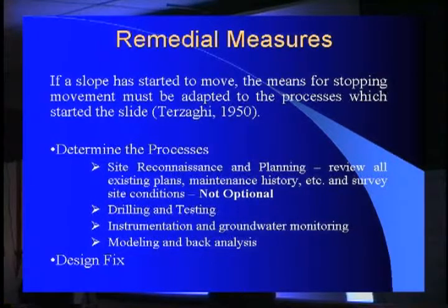Drilling and testing, again, is another very valuable tool in determining the process that caused the slide. It doesn't happen in every case. Sometimes what's occurred is obvious from a visual evaluation, and another restraint is time. Sometimes we just don't have time to mobilize drill rigs and do elaborate testing. I know that's not the ideal answer, but that's the reality of it a lot of times. So we utilize drilling and testing whenever we're unsure of a situation and want to define it further, or establish some sort of information for our analysis.